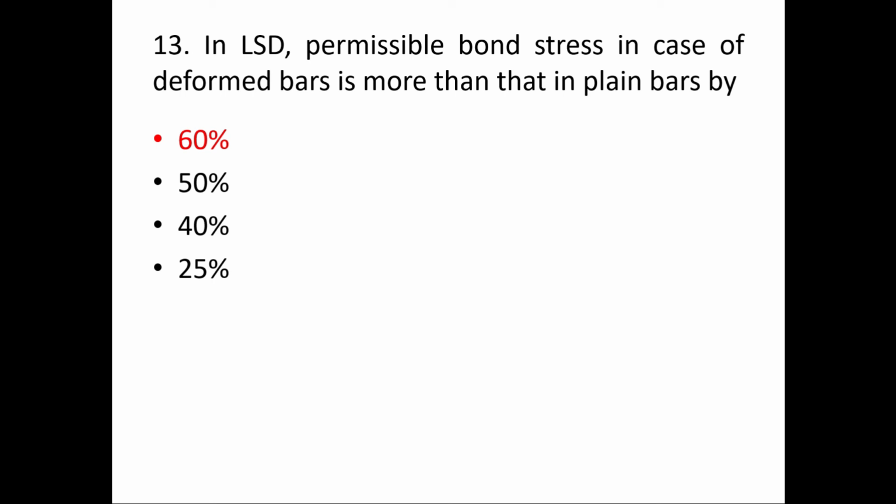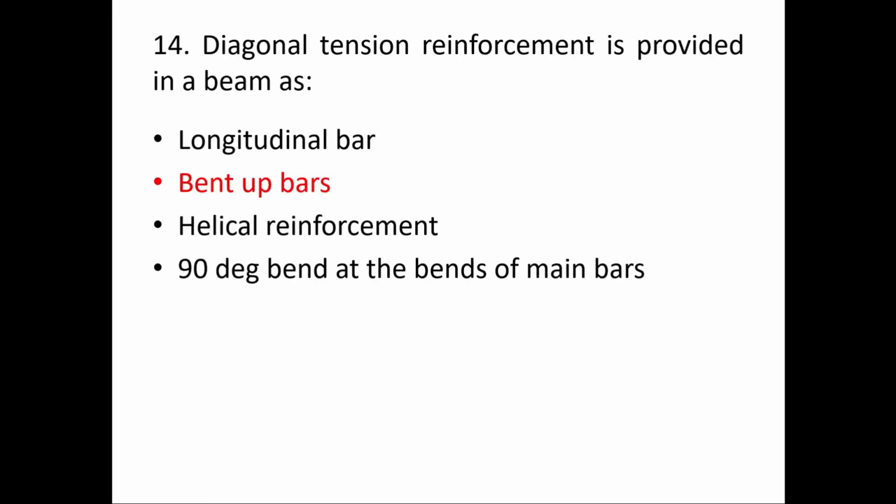So you have to keep in mind, for plain bars versus HYSD bars, our bond stress value is increased by 60%. And for compression, the values of bond stress shall be increased by 25%. Okay, so you have to keep in mind. Move on to the next question.